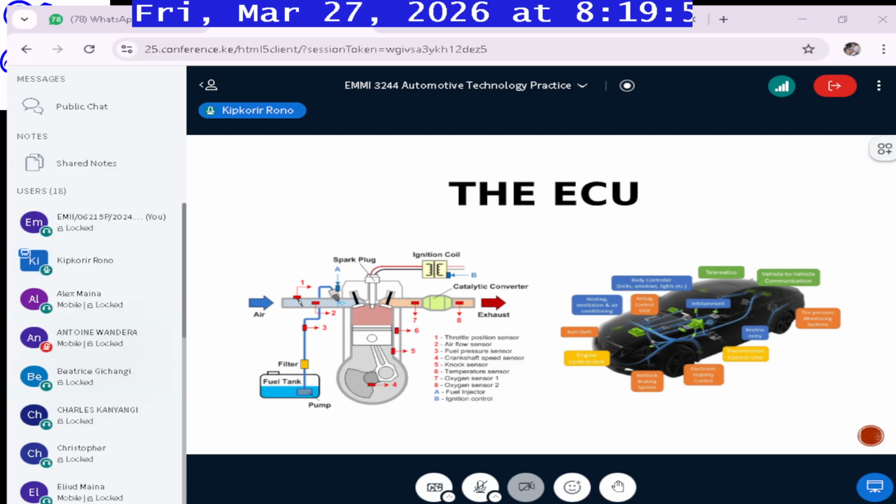So if it points to, for example, an excess amount of oxygen, then you could narrow down to the incomplete combustion process. One of the things you could do is change the spark plugs, change the type of fuel, or wherever you normally get your fuel, because the fuel could just be bad. Maybe there's some clogging in the intake manifold. Maybe you've not changed your filter for a very long time and it's getting clogged, so you're not getting a sufficient amount of oxygen and not getting the right air-fuel ratio, for instance. It could be that the spark plugs are worn out, or that the ignition coil is not functioning properly.